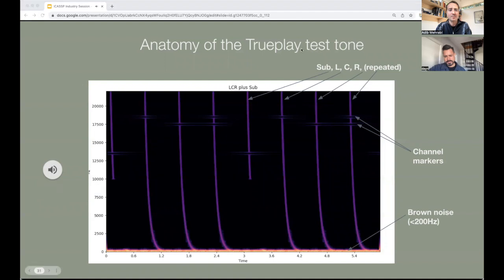Okay, so there are a few important aspects to this stimulus tone that distinguish it from the types of tones that are typically used for measuring speakers in rooms, for example, broadband noise or a full range ascending sweep. Once we decided to have the user continuously move throughout the space, taking the measurement, as opposed to making multiple static measurements, this immediately constrained the possible stimulus tones that we could use. A lot of in-room speaker measurement methods use broadband noise, and indeed this is what acoustic and audio systems engineers typically use when making in-room measurements of speakers. Random broadband noise could be used if the goal is to measure a single channel or an aggregate of multiple channels, but only with a measurement in a static location.